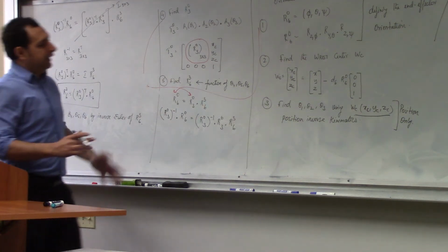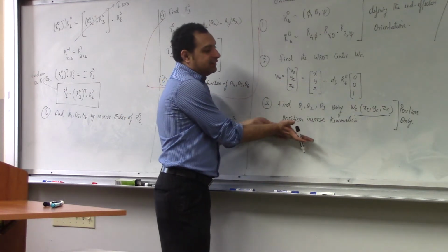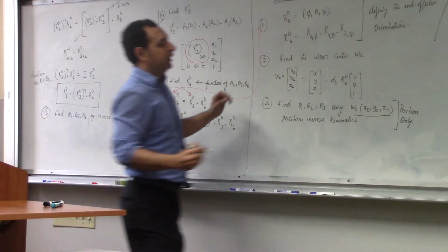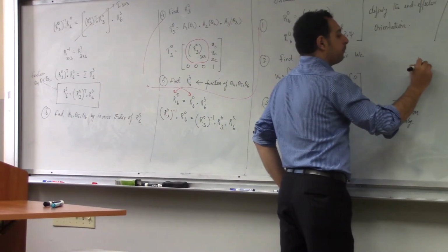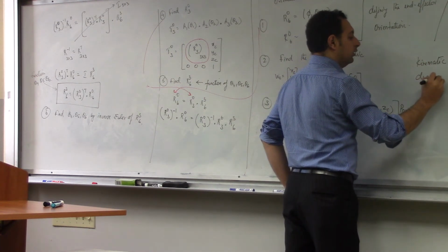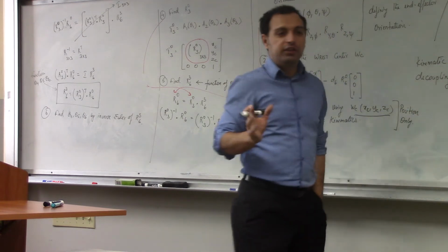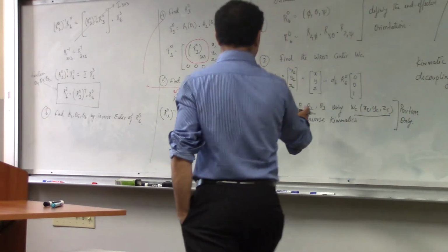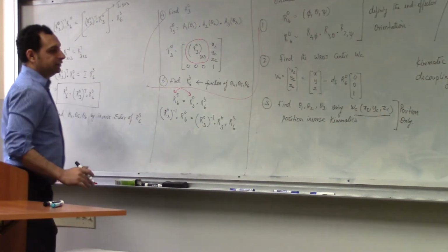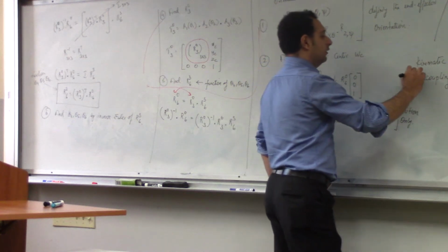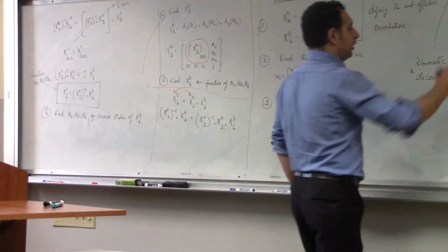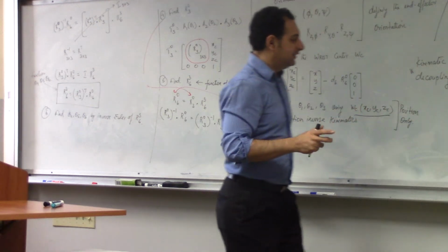The reason we call it decoupling is because at this point you're separating. This is position, and here you have orientation. So we are separating the two, which is why it's called kinematic decoupling. Okay, because we solve it in two parts. We assume that theta 1, theta 2, theta 3 will only dictate the position, and the other three will control the orientation. This is why we call it decoupling. This will only happen if three axes intersect at a point. You can only decouple a manipulator where you have three axes intersecting.